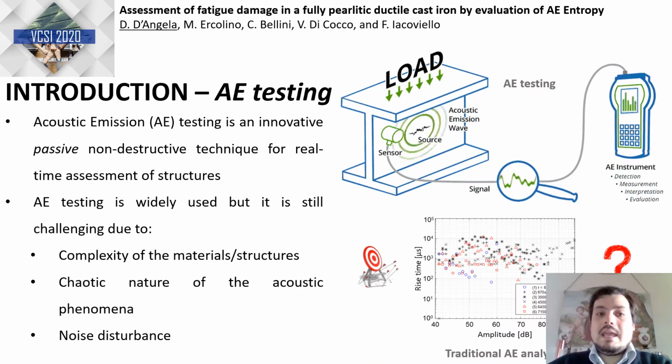Acoustic emission testing, AE testing, is an innovative, passive, non-destructive technique aimed at real-time assessment of structures. On the right, you can see a schematic application of the testing technique. You see the source of the damage that is emitting some energy release which generates acoustic waves. They are detected by the sensor attached to the structure, and they are processed and stored by the acoustic emission instrument. The analysis of the acoustic emission data allows to identify and localize the ongoing damage.